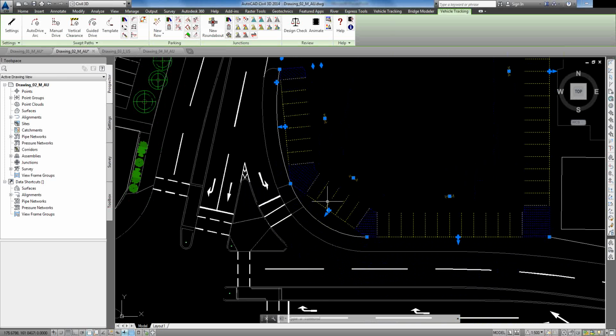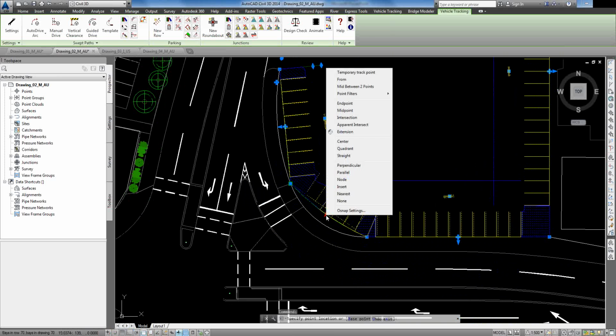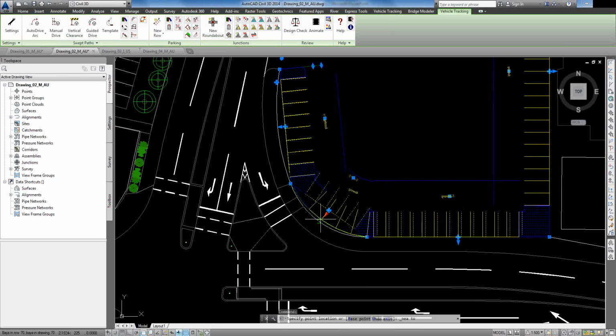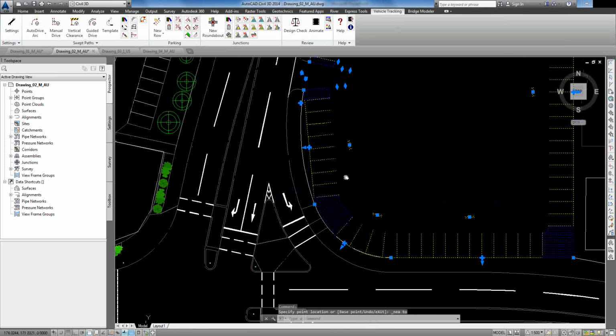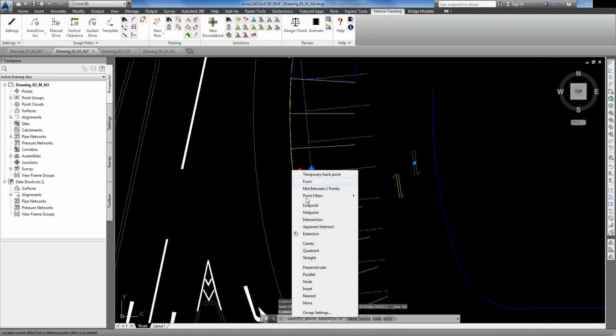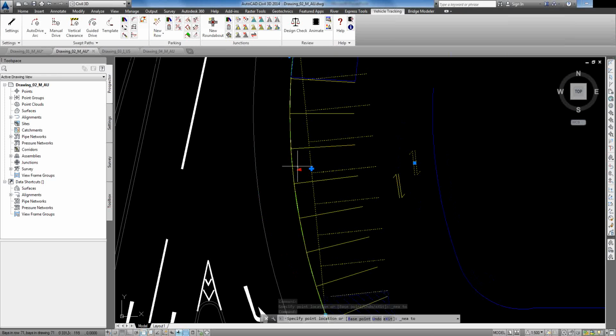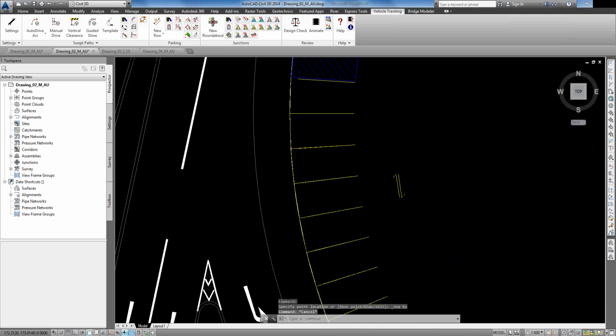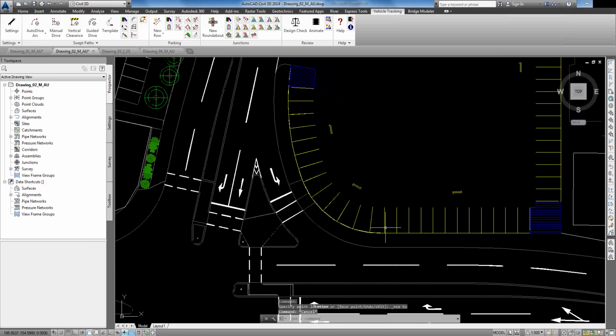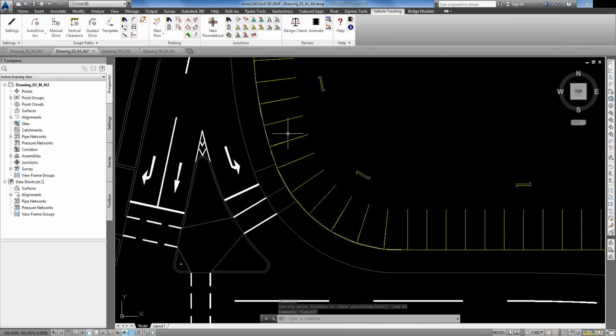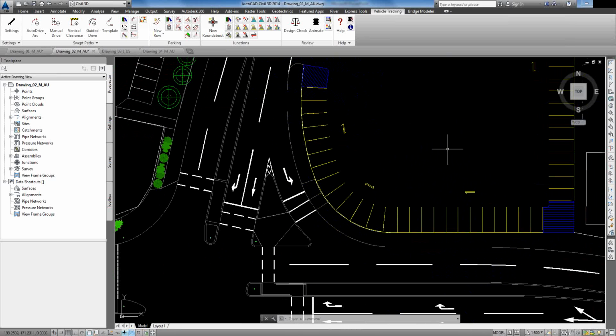Now, obviously these parks here, we would like to push those out to the perimeter, so we grab our grip and nearest, select the edge, then I'll come in, do the same again, nearest. And as we've done that, you can see it's now eliminated that island in the middle there, and it's still got all the appropriate spacing.